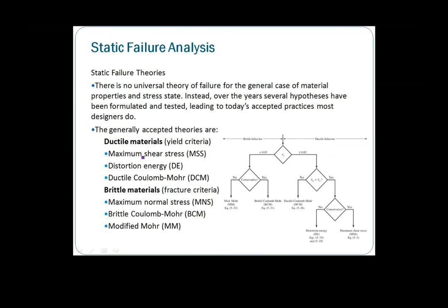Right, so we start with static failure theories. I suppose you have gone through this before, but here let's have a look at a few theories or criteria that we can use, available in ANSYS, that we can apply to evaluate our so-called designs. Of course, here we are saying that there is no universal theory; it all depends on the material itself and the stress that we want to use. Here we basically divide into two parts: ductile materials and brittle materials.